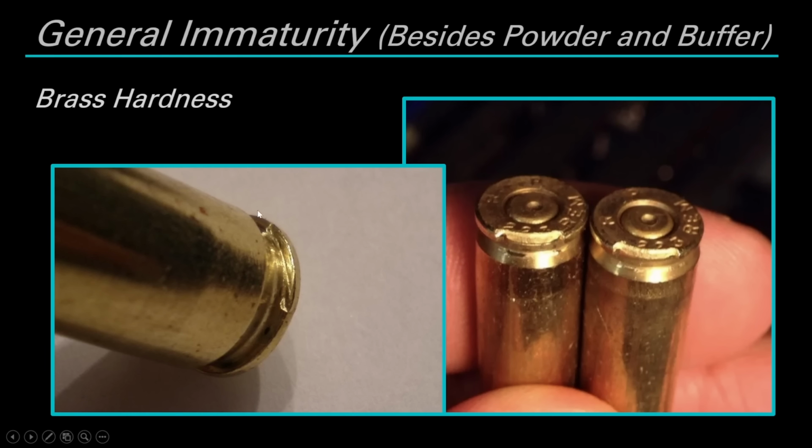And you'll typically see a deformation like this. Letting the bolt come back forward and trying to pull the case out slowly can sometimes result in this case still being possible to extract. The more severe failure that can happen as a result of brass being too soft is what's known as a rim shear, where the extractor just takes a bite out of the case, swages this entire section off, and then leaves you with a non-extractable case in the chamber. This case would have to be beat out from the muzzle with a cleaning rod, or removed from the chamber using a screwdriver or some other tool.